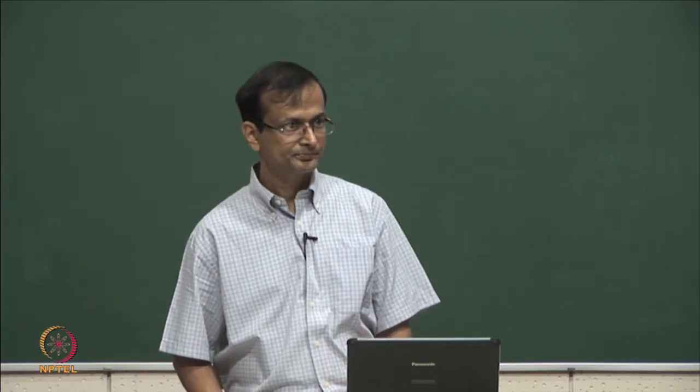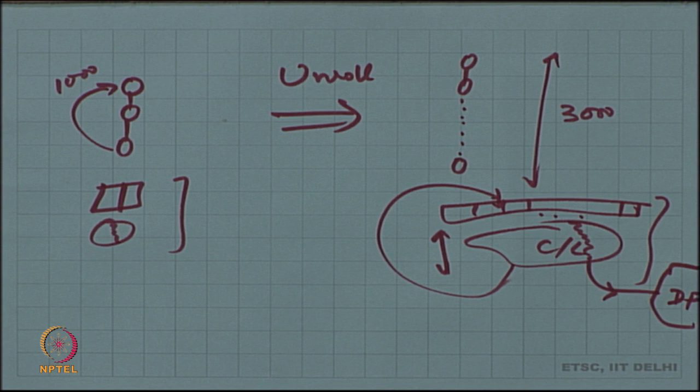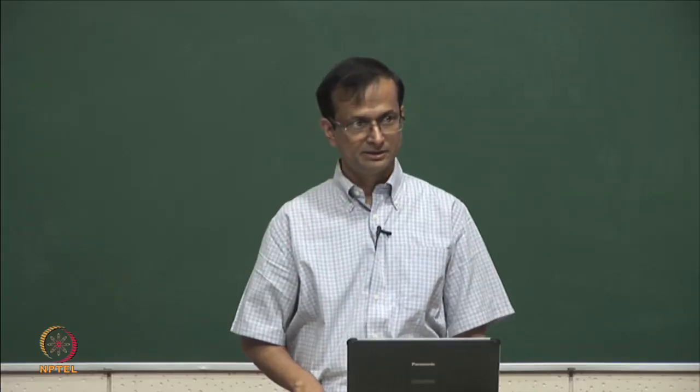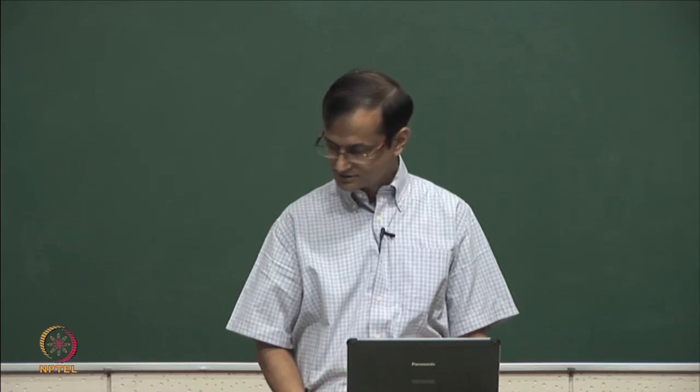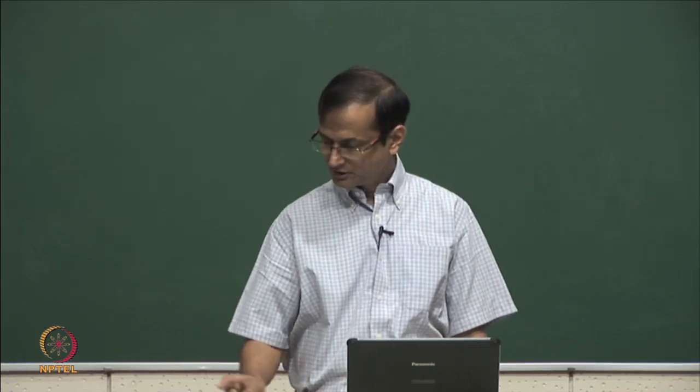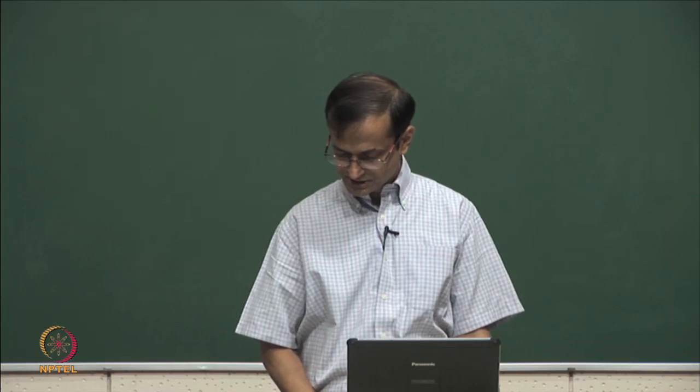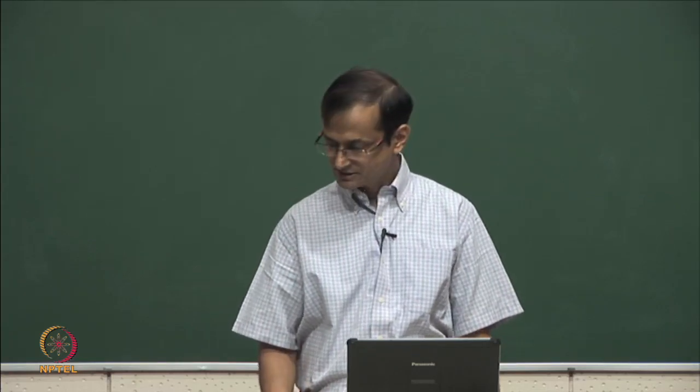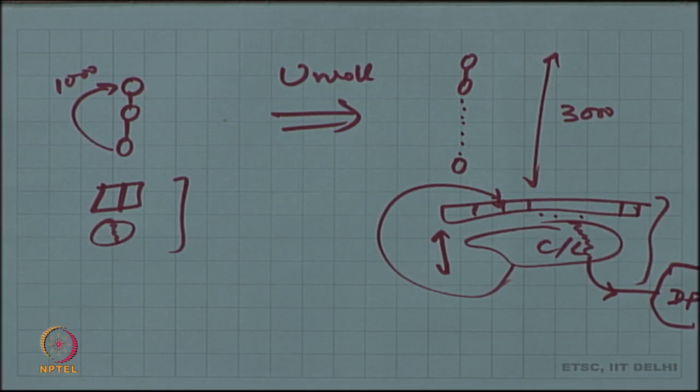So, this discussion came early on, but I did have some discussion scheduled for this at the later stages where we were identifying such phase ordering related issues in synthesis, but we do need to worry about this. So, in both the cases, compiler and synthesis cases, it does not make sense to arbitrarily unroll a loop even if you have all the information. Sometimes you do not have enough information.